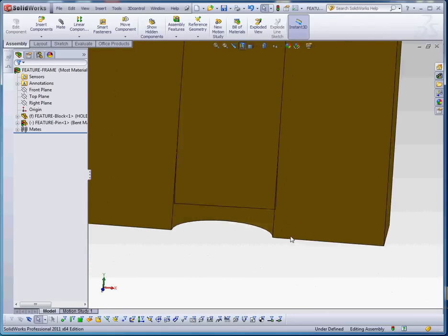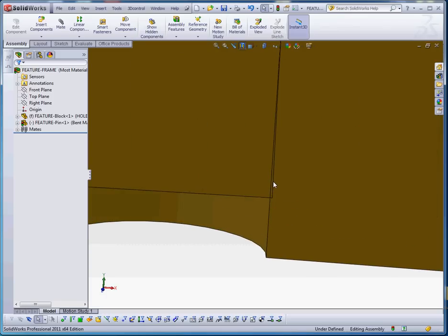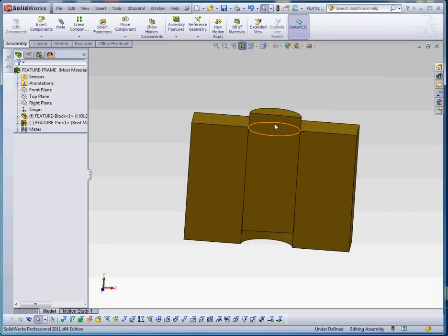And the same thing down here. Right down the middle, we have an appropriate amount of clearance, but down here we don't. We have interference there, and clearance over here. If we were to try to take this bent cylinder and put it in the hole, we'd have a difficult time. Now again, the diametrical dimension that defines this at each cross-section is true, but it's not cylindrical.